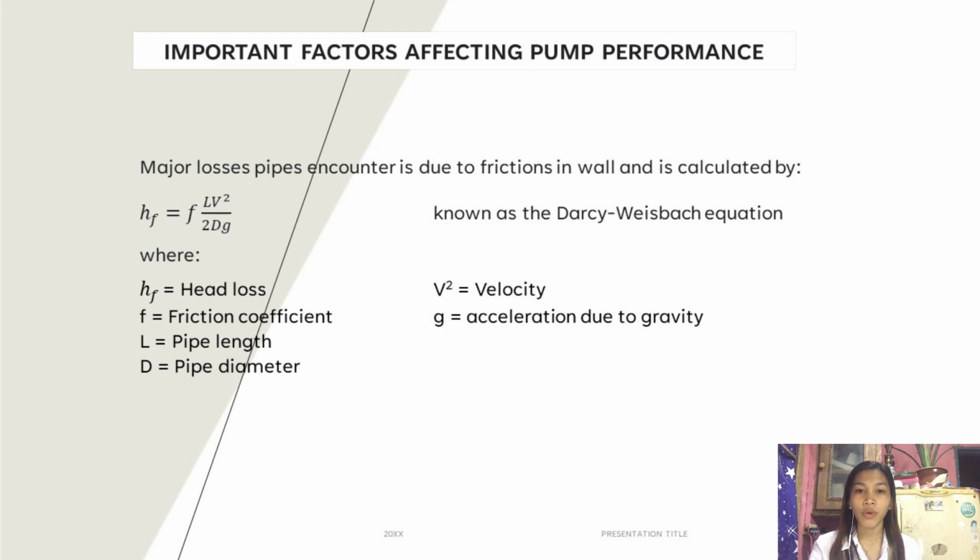This occurs from the walls of the pipe and disturbances to the flow path. This causes pressure drop in the system, which wastes pump energy. The amount of friction depends on the liquid type as well as the materials and the fittings used. Therefore, it is necessary to consider and calculate how much friction or pressure loss the system will generate, and ensure that the pump selected can overcome these mechanical losses. Otherwise, liquid cannot be elevated to the other end.